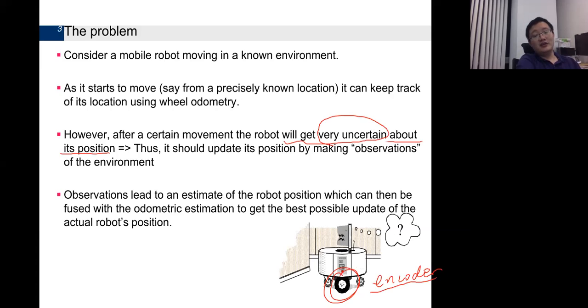And sometimes with a caster wheel structure, if you have two caster wheels and two driven wheels on an uneven floor, some of the driving wheels may be floating, because 3 points already define the plane. So if there's a hole on the ground, this wheel will spin without any actual motion of the robot. So the robot will get uncertain.